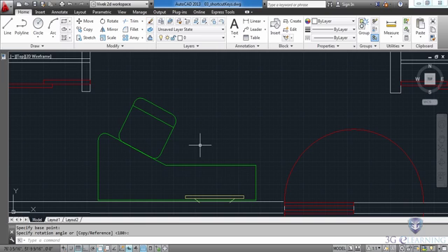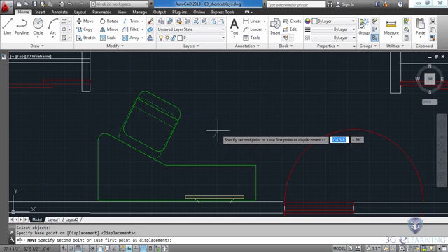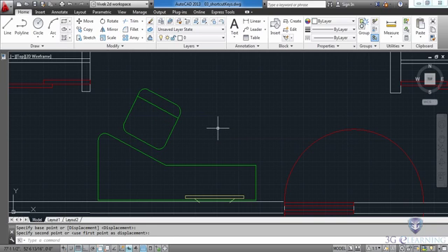Next, I would like to push the chair away from the desk a little bit. I will launch the move command for that. Select objects prompt, I will type P for previous. I will press enter to finish the selection, and I will pick the chair up from a point in space here and drag the chair away slightly. And I will click when I am finished.